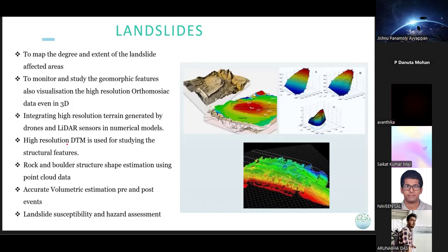Okay, so these satellite DEMs, which are freely accessible, have a coarser resolution, and it cannot give us accurate results because the landslide which happens is a site specific natural hazard, right? So if you have to get a detailed and in-depth knowledge, it is always better to go for high resolution data, especially when we are going to model the landslide scenarios.